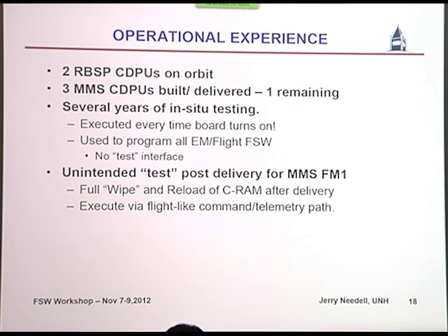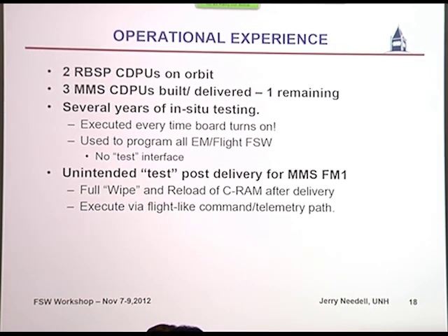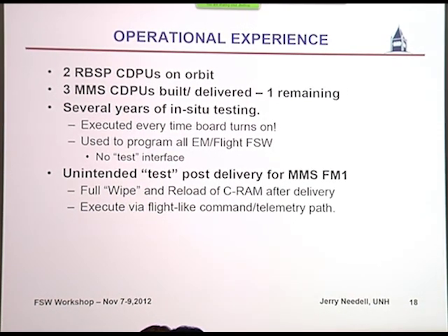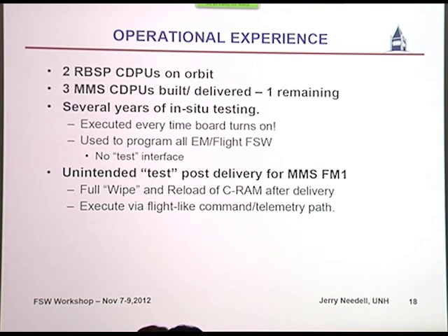So the decoding of the command is completely hard and fixed in the system? No, actually, at this point it's just a string of bytes coming in, and the decoding of the command is done in the flight software. The only commands decoded by the hardware are those where the FPGA looks at the CCSDS header and pulls out the opcode. If it's one of 2 opcodes, it knows what the next 32 bits contain, and it'll react to it. Other than that, it just passes it through.